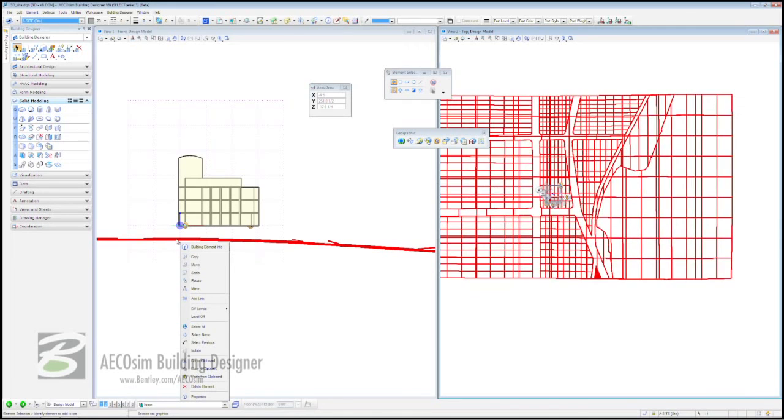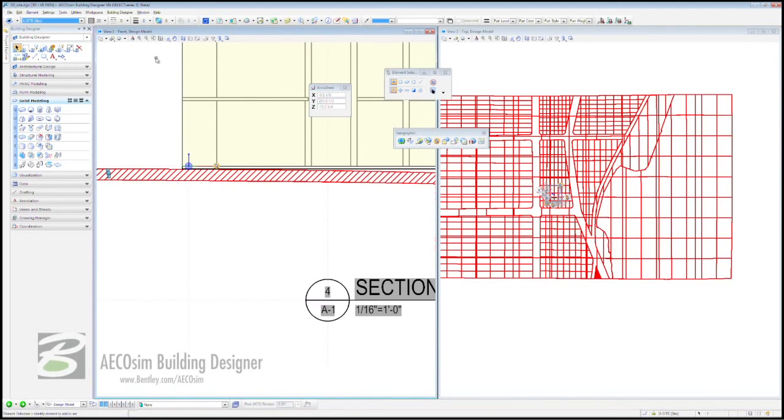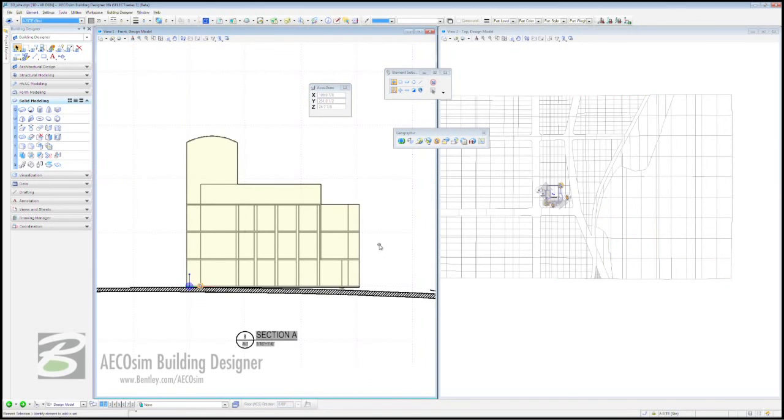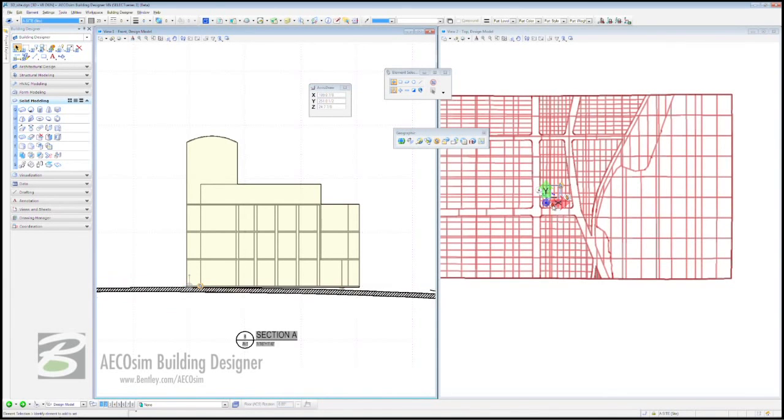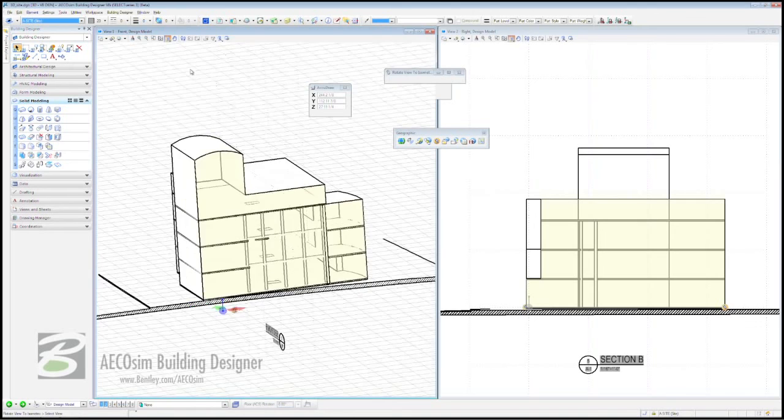So what we need to do here is select our terrain, move, right to move, and now it's just a matter of moving this to meet the bottom left-hand corner of our structure. And obviously when we do this, there has to be some fill right underneath the right-hand portion of our structure. But we can also come into any of the views. If we turn this to the right-hand side, again, we get another sectional view of it. Let's rotate this back to an isometric.